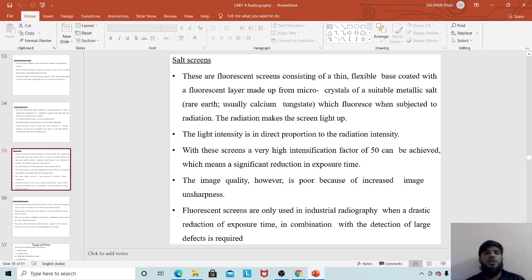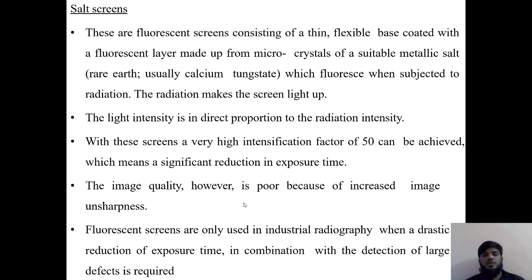So the importance of these screens is that when the screen is first exposed to the X-rays, the screen will release some kind of electrons or radiations which intensify the image. So the image quality is increased by using the screen itself. Here you can see the image quality, however, is poor because of increased image unsharpness.